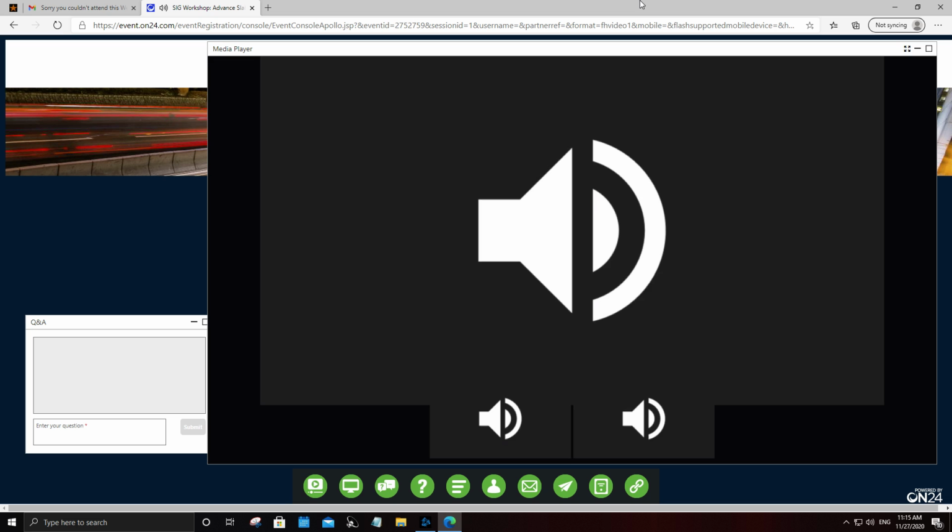There is one question: how does it transfer seismic moments from frame analysis back to the flat slab? So that's not back, that's one way actually. From RAM Structural System, it is possible that it transfers at the slab-column junctions. At those points, it actually transfers the seismic moments and the shears. So that happens with the integration of RAM Structural System and RAM Concept.